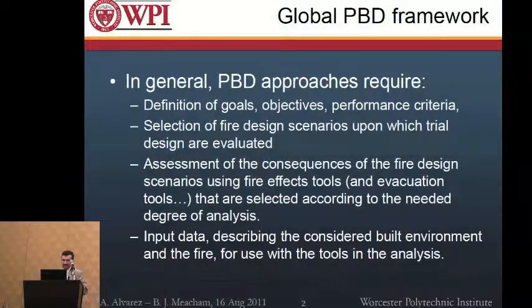So, in general, the performance-based design approach for fire protection design requires the definition of safety goals, objectives, and performance criteria. The selection of fire design scenarios upon which the trial designs are evaluated, and the assessment of the consequence of the fire design scenarios using the fire effect tools and also evacuation tools, which are selected according to the needed degree of analysis required for the performance-based design. Of course, input data are needed also in order to use these tools.